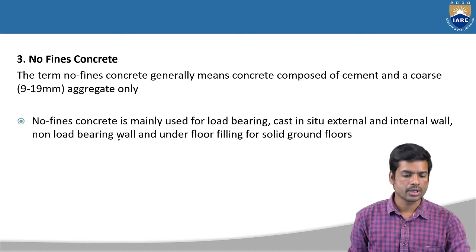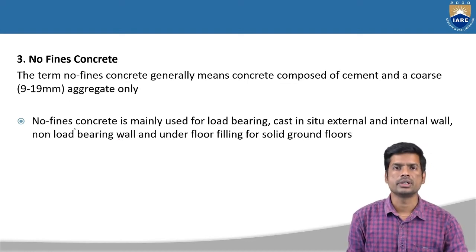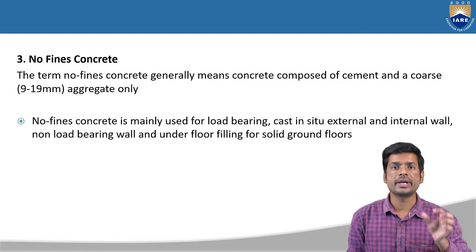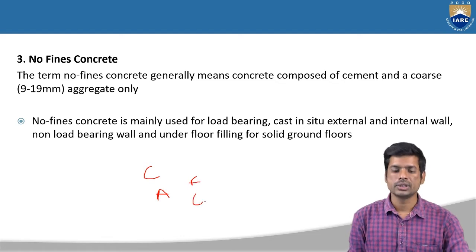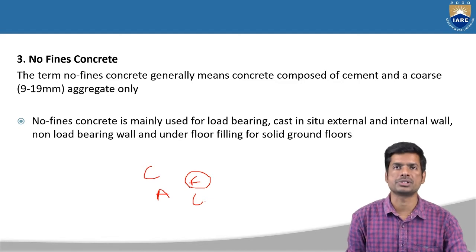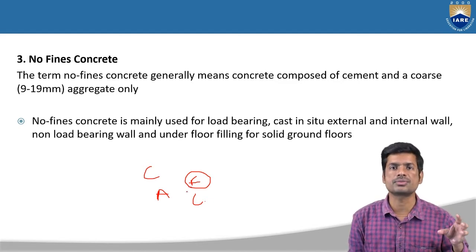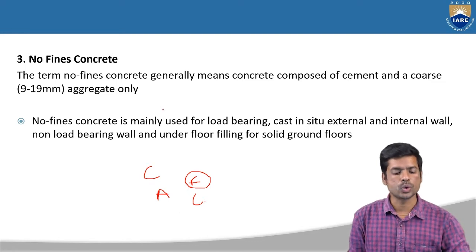Okay, and next one, no fines concrete. Here, no fines concrete means we are not going to use fine particles, that is fine aggregate. In concrete we have cement and aggregates. In aggregates again we have fine aggregate and coarse aggregate, right? So here we are not going to use this fine aggregate in the concrete preparation, that is no fines concrete. So without using this fine aggregate, we are preparing no fines concrete.